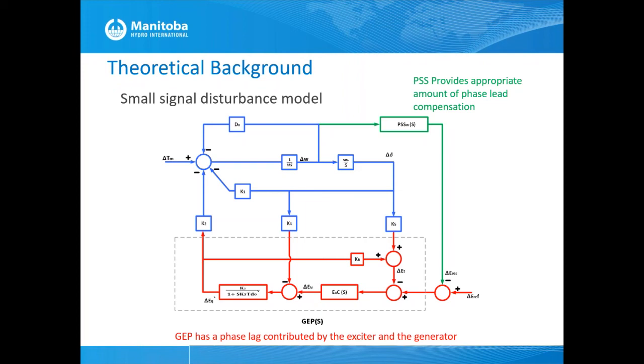Now, damping is a different situation. For the same inertia, damping is about the phase of the resulting torque. It may be the same magnitude of torque, but it is the phase that matters. If it is in phase with delta omega, we call it damping torque.